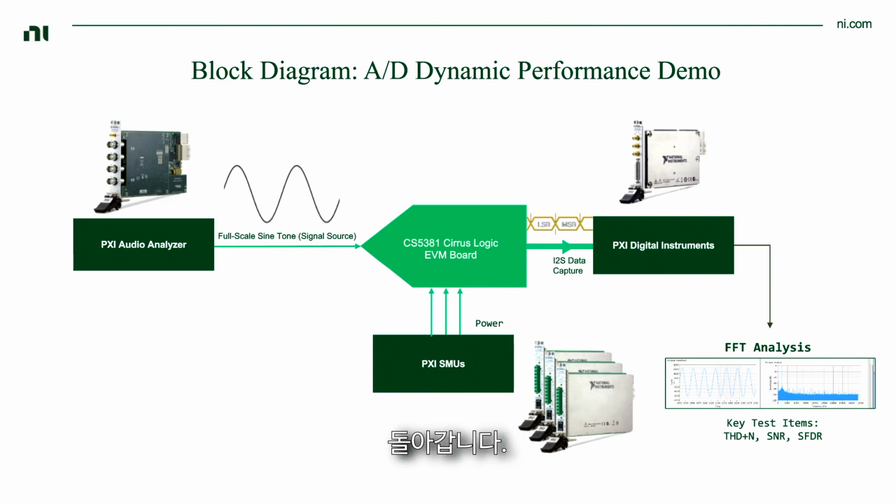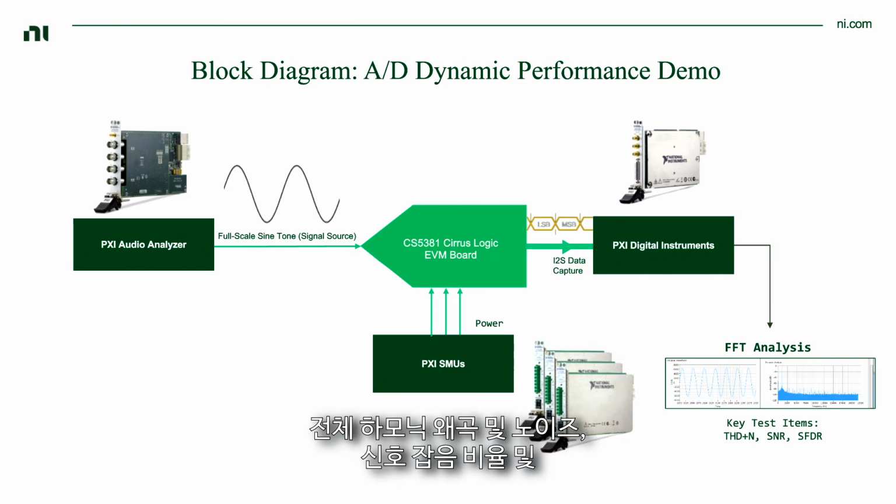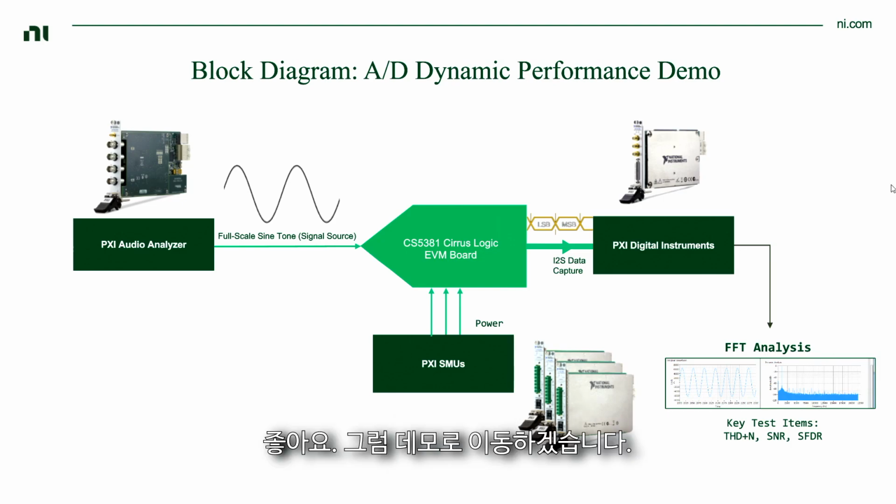And then back on our host PC, we're analyzing that data, we're performing spectral analysis, and we're returning key measurement parameters to the user, such as total harmonic distortion and noise, signal-to-noise ratio, and spurious-free dynamic range. Okay, so let's jump to the demo.